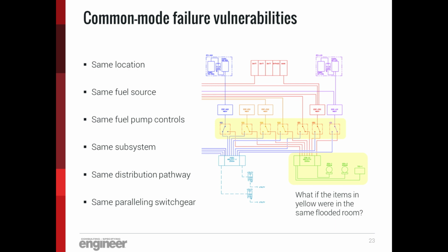Let's talk about different subsystems. Let's say your subsystem is, for example, critical branch, or to be a little bit more precise, you have a riser or a couple of risers coming out of the distribution panel further downstairs. If you lose the distribution panel, you've lost both risers, even though the two risers may well have been intended to be redundant to one another.